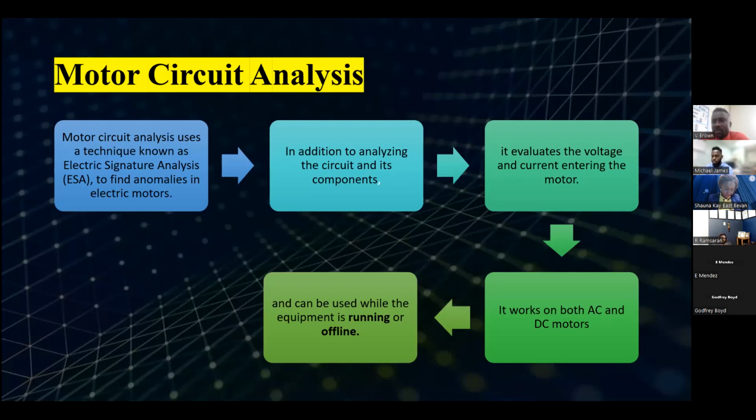That means I can tell if the supply is clean, a good intake supply coming in from the source. Imbalanced voltage and imbalanced current limit the life of your motor by cutting down your winding life, operating at higher temperatures. Again, we use the thermographer to find these high temperature points in the motor winding. And if the bearings are going bad, we use the temperature gun or the thermography camera, and you can find these things.